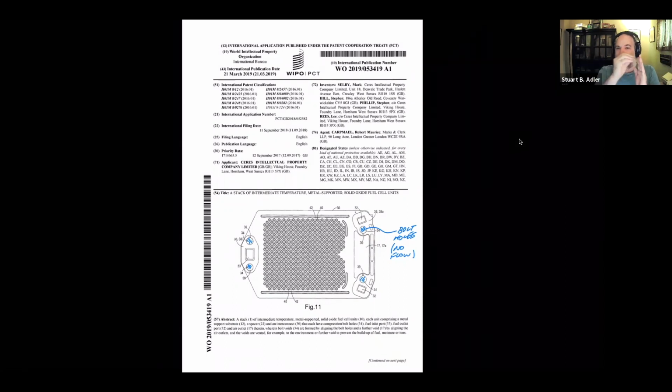So it's going to have a flow rate across it that's given by the delta P from one side to the other. Well, if you go up the stack even further to the top, that's separated from the bottom by some distance. And there's pressure drop as you go up the stack, and there's pressure drop as you come down. And so if you go to the very top, there'll be a different pressure drop. And if it's a very tall stack with long manifolds, that pressure drop difference can get really big. If the pressure drop is not the same, then the flows are not the same. You've got more fuel going to one cell and less fuel to another.